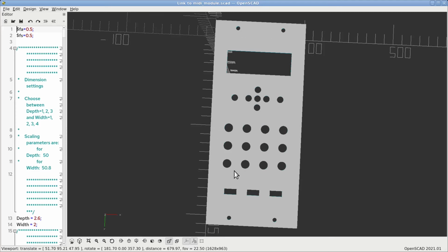These control voltages are generated from the control change MIDI messages, generated when we use the knobs of a controller, like those in the AKAI LPD8. I have actually decided to have 8 of these outputs, so I can fully use all the knobs in the controller I own.